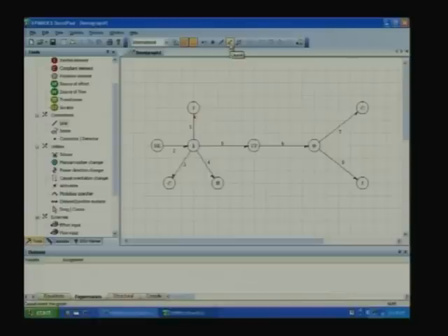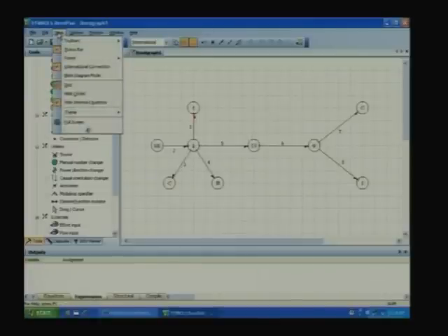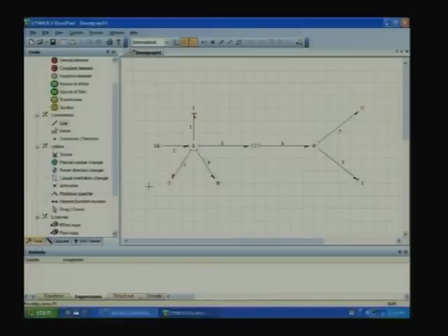Now, this is the icon for causality, that can also be done in an algorithmic way. So, I press it, it has already given the causalities, probably because these are all circled. So, I will hide the circle, view is hide circles. So, you can see that this is properly causal, the stroke is here, SE is receiving the flow, C is receiving the flow, R is receiving the flow, flow is going this side, flowing that side, exactly as you have done on the paper, it is causal that way.